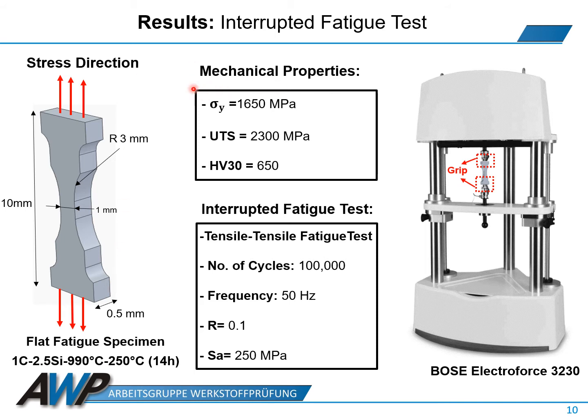The mechanical properties of the alloy are written in the box, and the tensile fatigue tests were carried out on fatigue specimens after inducing a notch behaving as a short crack by means of the focused ion beam technique in order to define the crack initiation point practically, and also to analyze the crack path within the short crack regime where the local microstructure governed the fatigue performance.